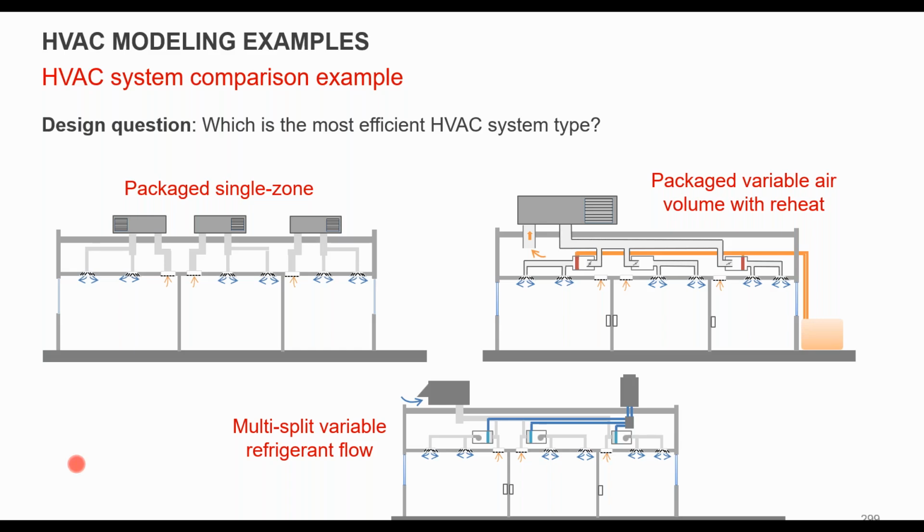So where are you going to get data here? Again, you might have some basic massing, so some drawings. You might be getting a little bit of code data. For example, they might not have ventilation determined at this point. This is still high-level schematic design, so you might be calculating it like we did in the previous example of ventilation. You might be pulling manufacturers' data because they might not have selected equipment yet, so you might have to go to each manufacturer's website and find the data. We'll step through all of these.